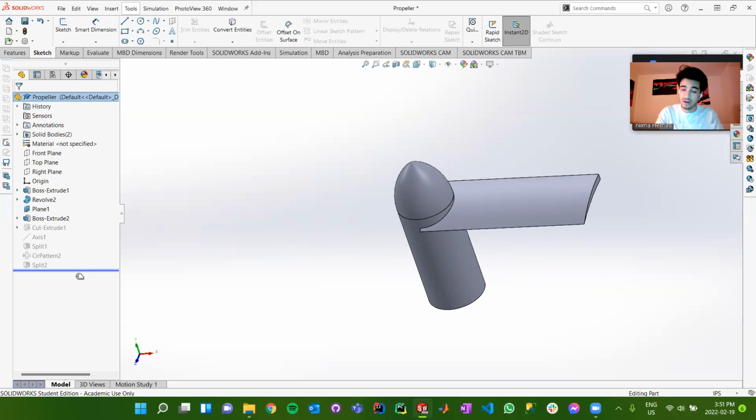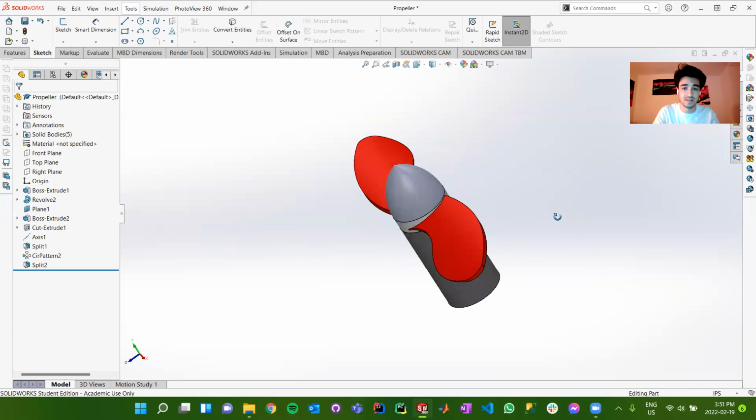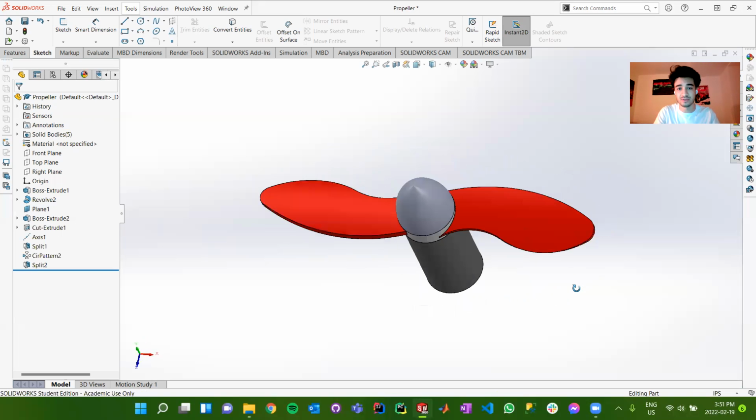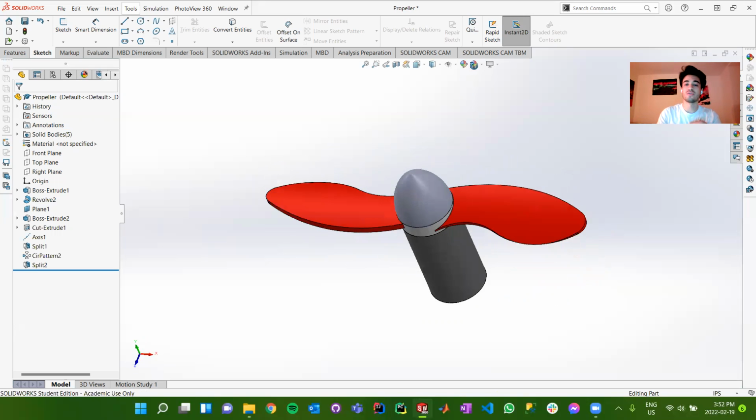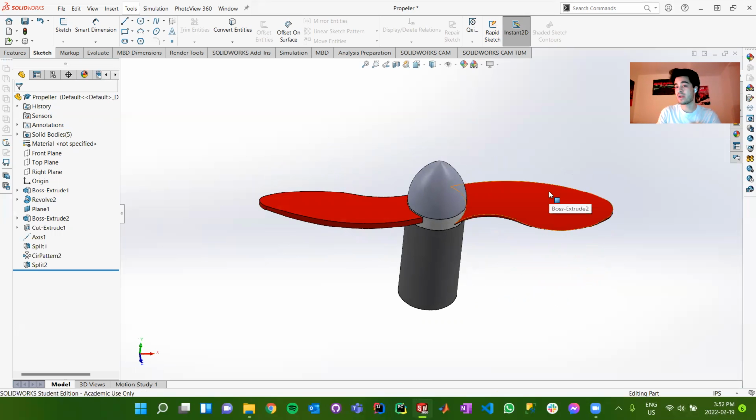So if we go and undo all of the step backs that I just implemented and we go back to the actual assembly, we'll notice that we have these two different wings or blades essentially. And the way that I like to approach problems like this is I think, okay, how do we deal with this in terms of projections, right? This is a complicated shape to try to do all with either one sketch or a set of splines. You're going to waste a lot of time defining a bunch of arbitrary points that you're not sure is even going to yield the right result.